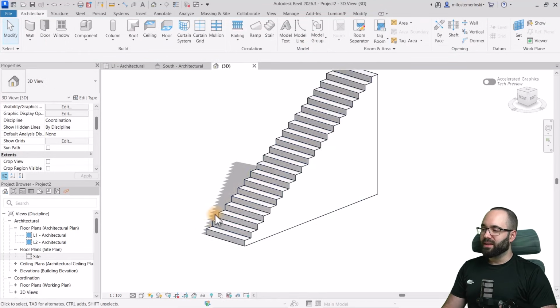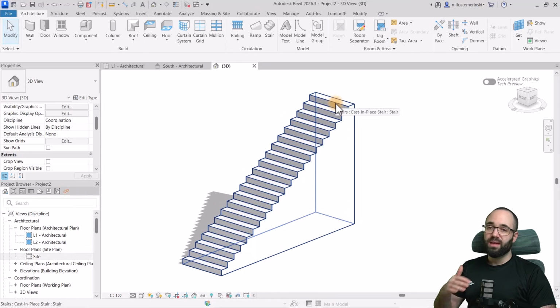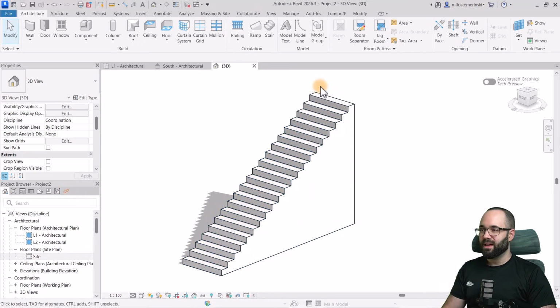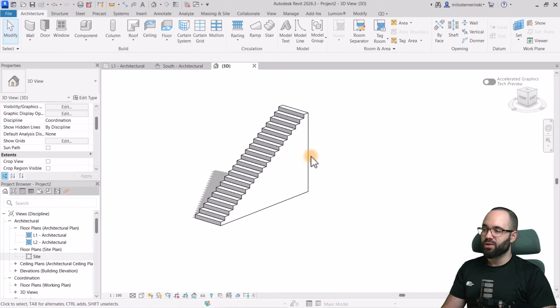We're going to be creating the seating at every 3 risers. So that's why I went with 22, because that's 21, which is divided by 3. And then we have plus 1 because Revit tends to use the floor on top as the final riser. So at the end, we have 21 risers. And also I've set the depth to 4000 millimeters. So this is filled out with that stair.